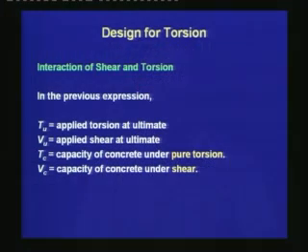In this expression of the interaction equation, Tu is the applied torsion at ultimate, Vu is the applied shear at ultimate, Tc is the capacity of concrete under pure torsion, Vc is the capacity of concrete under shear.